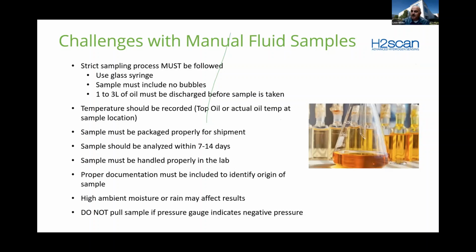Sample, of course, must be packaged properly for shipment. Labs get samples all the time with broken sample containers. Ideally, your sample should be analyzed within 7 to 14 days. Gases like hydrogen, very tiny molecules, can leak out of the sample, so it's best if the labs can analyze the sample within 7 to 14 days of the sample actually being taken from the